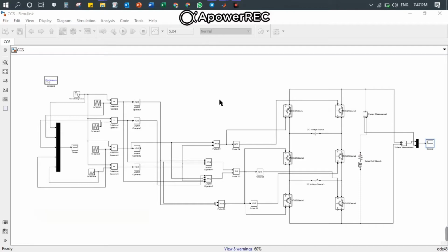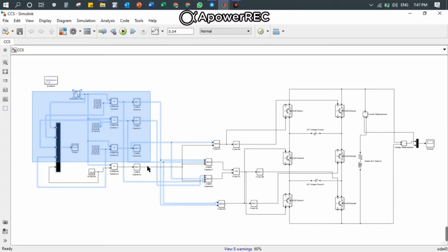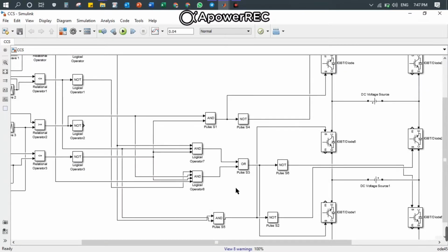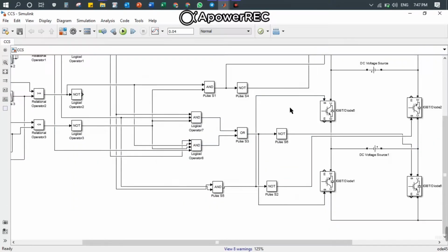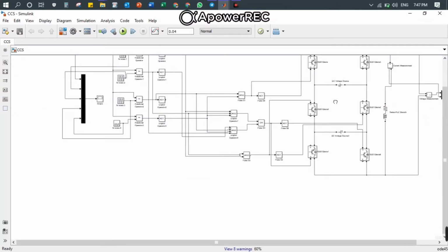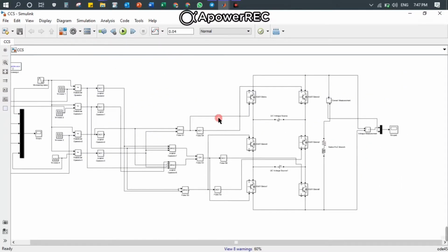Now, we move on to cross-connected source multi-level inverter. Similar to the previous H-bridge inverter, the same PWM circuit is being used. The only difference here is the additional logical component to ensure that each switch will have the desired switching pulse. Since the required number of switches is 6, the original PWM pulses have been reduced from 8 to 6 pulses by using the K-map method. This is to ensure that the process of closing and opening the switches will be accurate and follow the switching state.